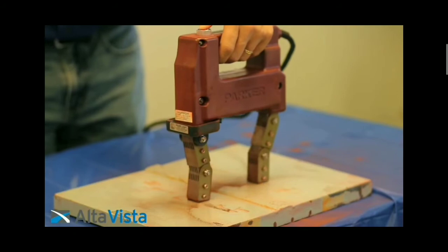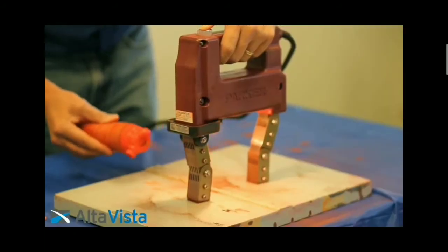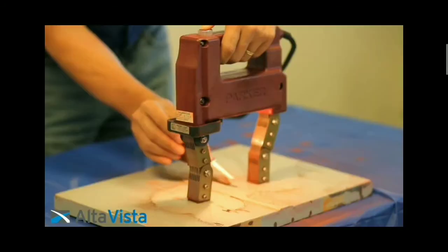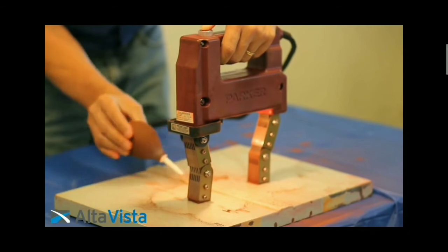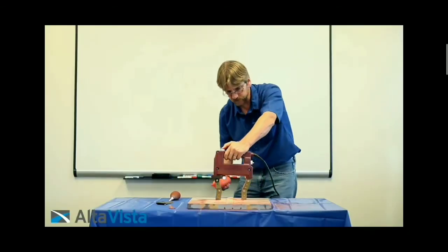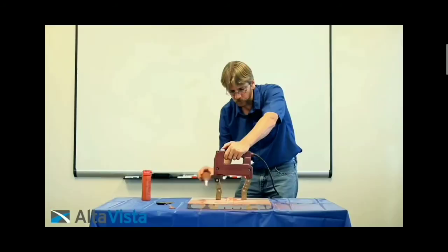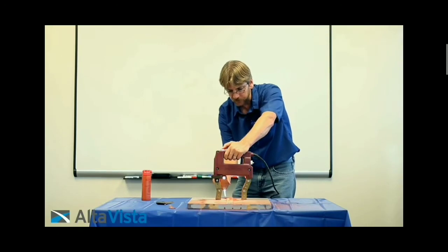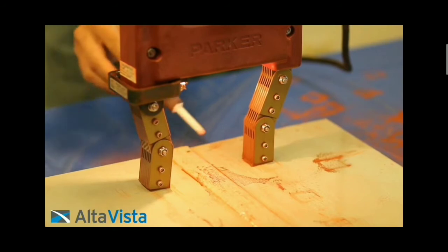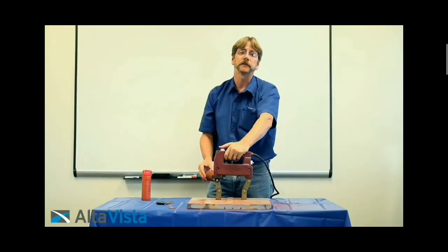We're going to move down across the plate, making sure that we have overlap, so I make sure that I test 100% of this particular component. I don't see anything there. I'm going to move down again. And as I apply this here, we actually start to see the formation of an indication along the toe of the weld. That happens to be about a 2-inch long crack in the heat affected zone.